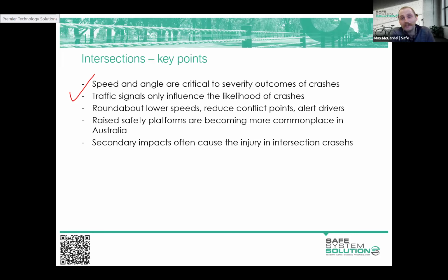If you were to have a scenario where you did need to create compact roundabouts and also support pedestrian movements, I mean, it can be done. You'd basically create the raised component as a wombat crossing, so you'd have the zebra markings there. You might also do some flashing lights or something like that, just so it's very obvious that it's a pedestrian crossing point. But it would depend on what type of context you're looking at. It's unlikely you'd be doing that in those rural settings because you don't have that pedestrian demand.